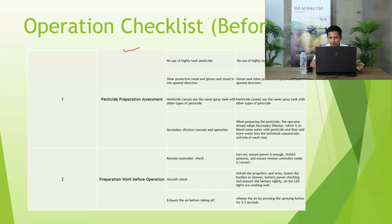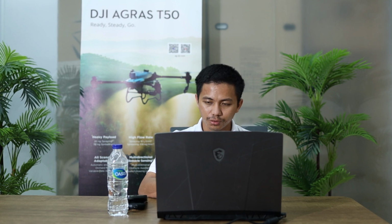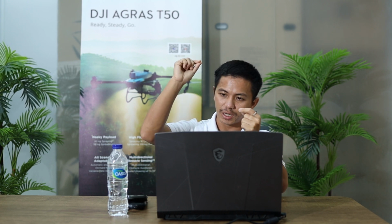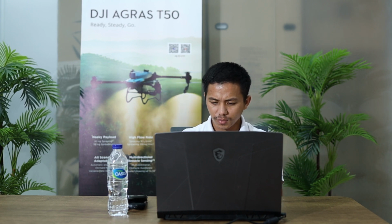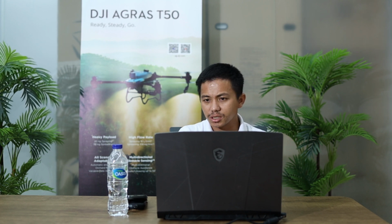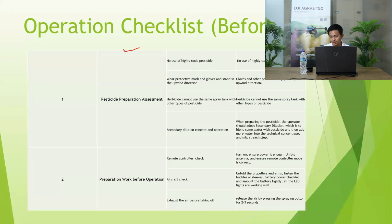Next, for preparation work, we have 3 checks. First is the remote controller, second is the aircraft, and the last is you need to exhaust air. Why I add only 1 point, exhaust air, is that many pilots forget this. If you forget to exhaust air, there can be some air in the hose, and in the initial stage, when the drone takes off and starts, sometimes there is an error and it might come back because the system is not working. But this is the worst case scenario.